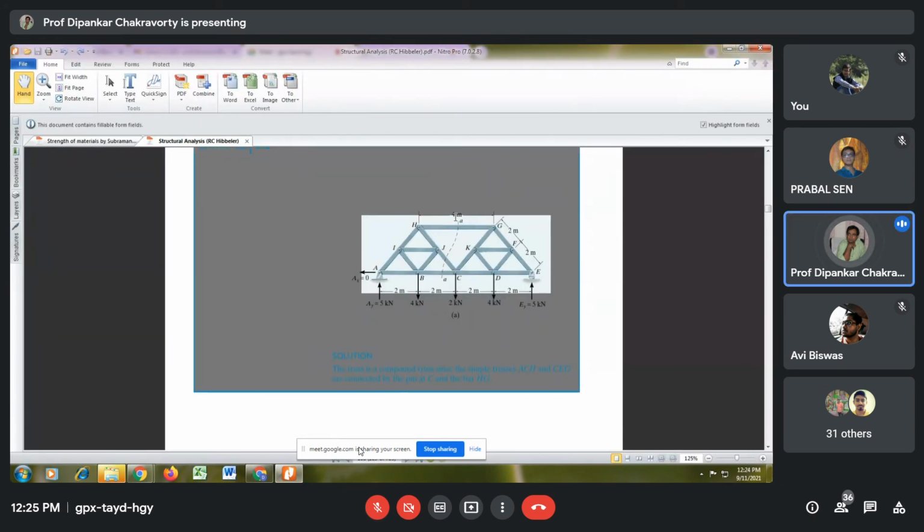So once HG is known, can you hear me? If you come to joint H, then tell me, can you solve HG and HI? Because there are only two unknowns. This member is known, so this and this I can solve. So what to do next? Tell me. You come to joint B. BA was pre-known to me. BC is known by method of sections. So can I get BI and BJ?